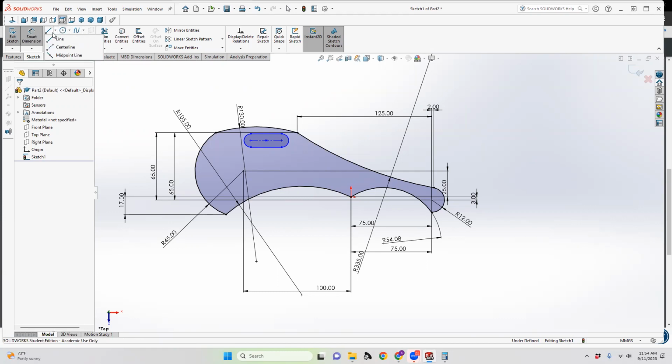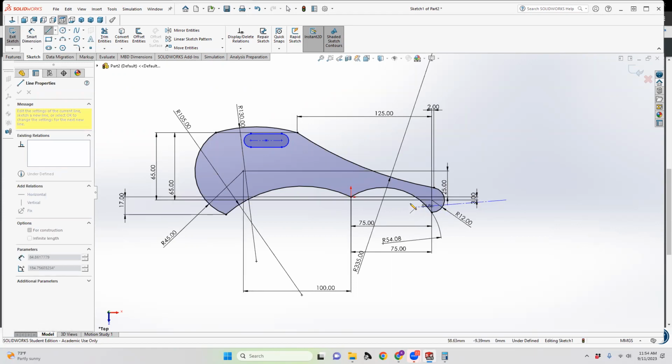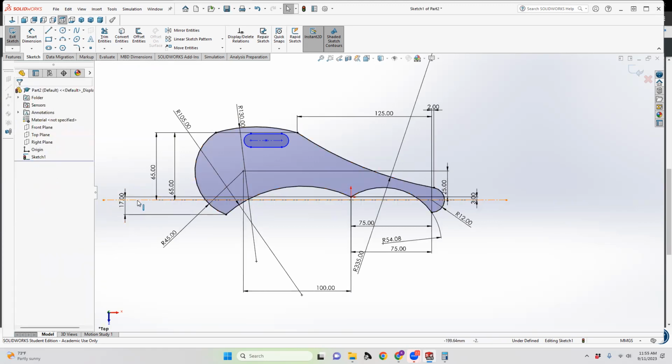But a center line is going to be really useful as a reference point. A lot of times what you want to do is drag it somewhere out here where it's not actually touching one of your other center points. It can be parallel to, but you want to drag it out so that it's parallel. Sometimes you'll have an intersecting point and parallel, and that's an okay reference to have. The center line, because we've run that through a point that was already fully defined, becomes itself fully defined instead of staying blue.